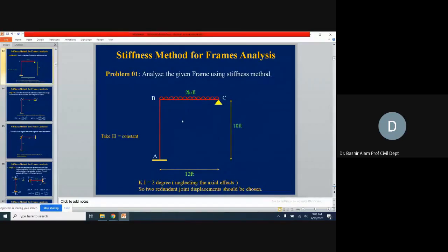This is the original one. How is this beam going to deflect? It is going to deflect with a concave shape near this support because of this loading. So now if we draw a tangent and draw a curve starting from the original position to the deflected position, you see how the actual rotation is going to be.